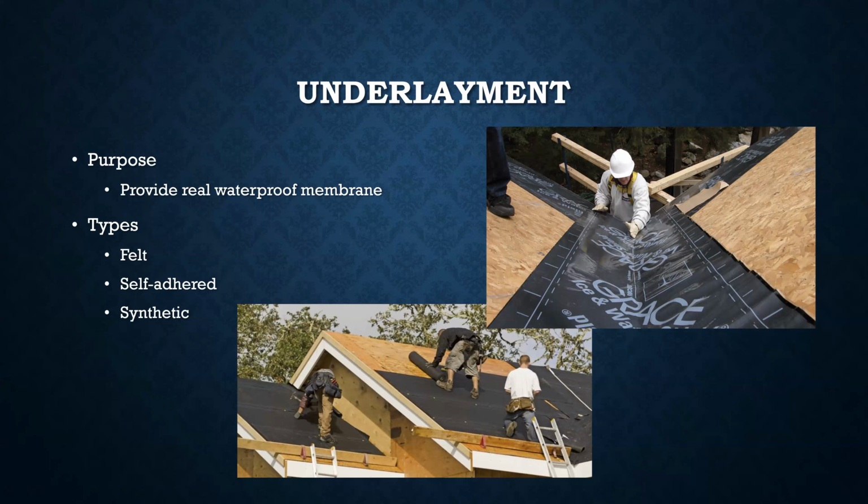But effectively, if you've got snow on your roof and the sun comes out and starts to thaw everything, it's going to start melting all the snow on your roof, which is going to turn into water. The water is going to run down the roof, and then it's going to try to go all the way to the eave, but the eave is overhanging the house. It's not part of the house, and if it's cold outside and snowing, your house is likely warm, so your attic is also warm. So you get this water running down your roof from the attic being warm, and it gets to the eave where the eave is cold because it's outside.